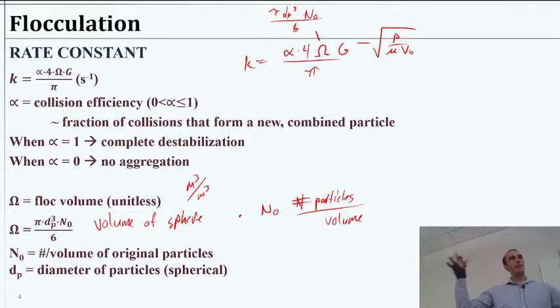So with those pieces of information, it's all stuff we could solve for. Just have to know what term is describing what. Then we can know the kinetics of how quickly the particles are meeting. Therefore, how long does it take for them to grow to large enough to sediment out of solution? So this can kind of pull all these pieces together with sedimentation and how to design it.